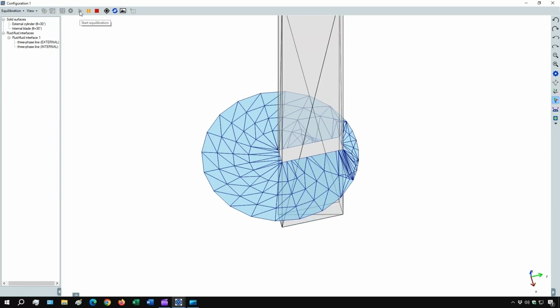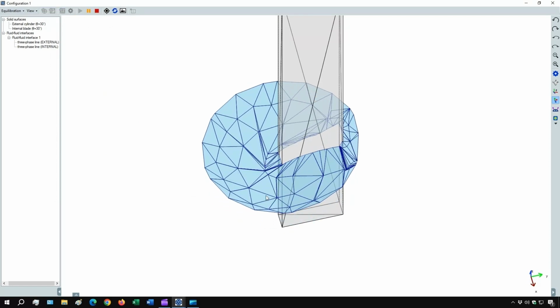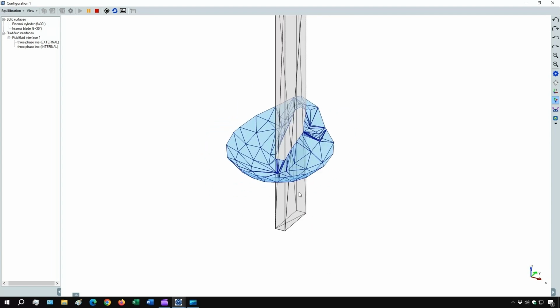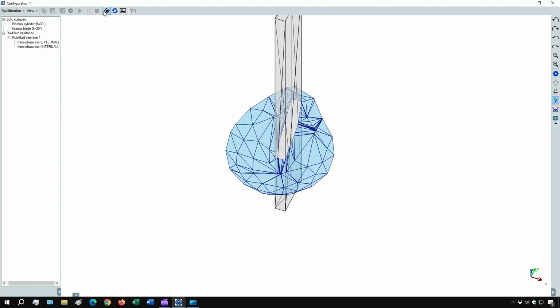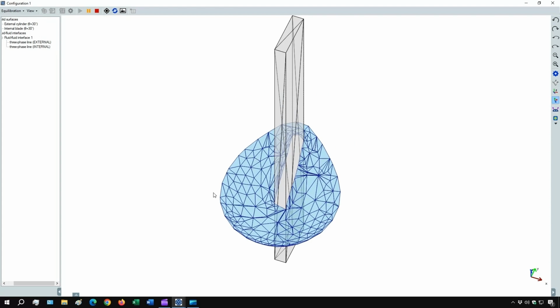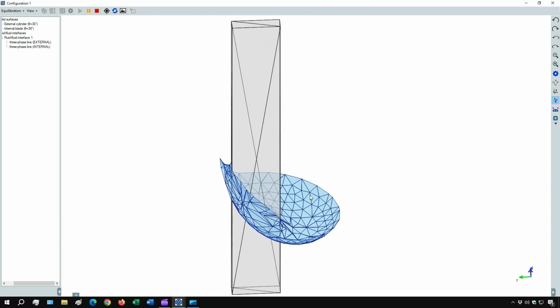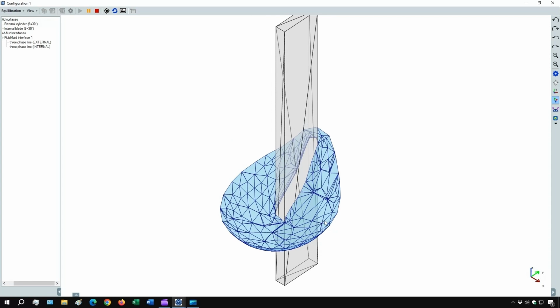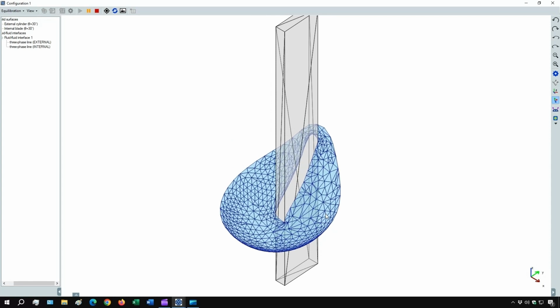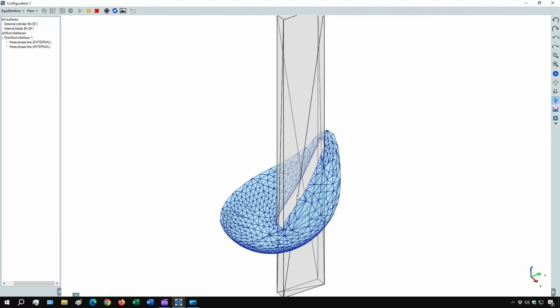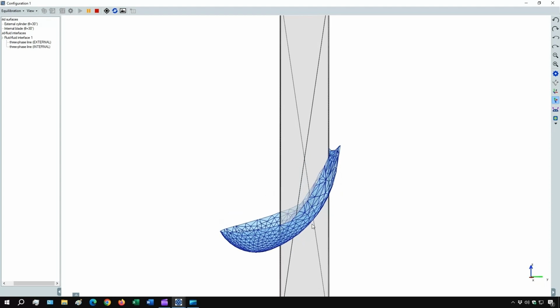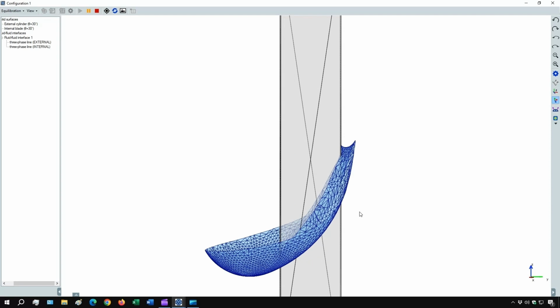This time, differently from the previous examples, the initial shape of the fluid interface mesh is far from its equilibrium shape. In particular, the fluid below the interface wants to fill the whole interstice between the blade and the external cylindrical surface. So the fluid interface mesh will keep rising until the top of the blade. The automated method to refine the mesh is supposed to trigger the mesh refinement when it detects that an equilibrium has been reached.